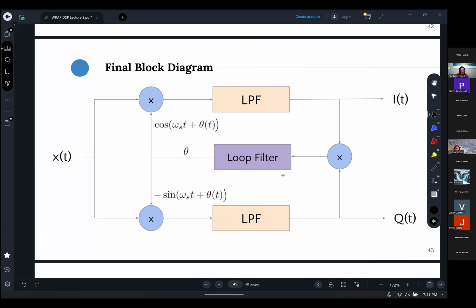But say we take our signal, just hot off the ADC. We don't know what anything means yet. So then we're going to demodulate one sample, just a singular sample, with our generated cosines and sines. This is just as normal, right? And then from that we low pass it, so then we get our received I and Q components, but then we take the results of these, the I and Q components, we multiply them together, and that's our error term.